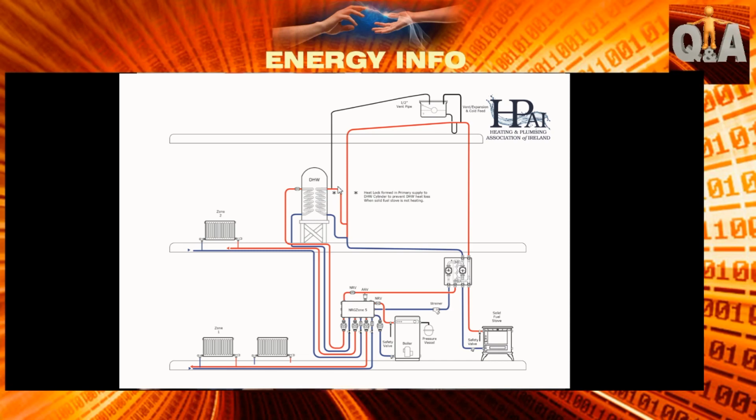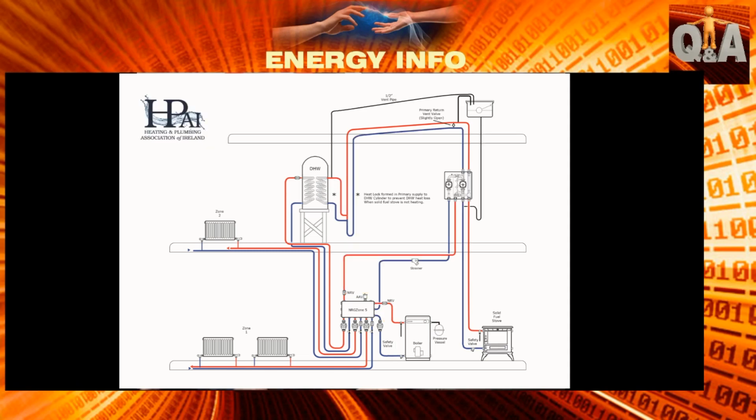Again, this is just a similar situation where you have an open primary circuit passing through an energy link, but that really isn't the point. The cold feed is what's important there. Do you see how it's brought down? So it's the last connection on the way back down to the stove. So if water is expanding and pushing, the cold water can travel down through the cold feed and get at the stove to cool the appliance.